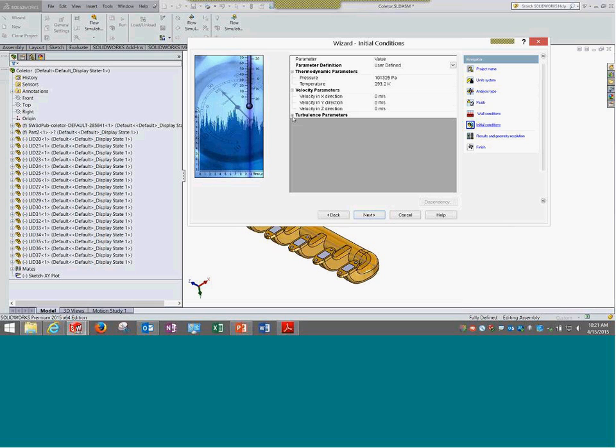Okay, there are different ways, but one of the common ways by which I explain this is that we are asking the software to start from an initial scenario. So when I start this analysis, the software does not know where to start, and it basically starts from zero, or ambient pressure and ambient temperature. However, if you have taken those initial conditions from some other project, or you are manually giving them to the software, honestly, you are helping the software to start with a closer solution, and then it can further iterate to give you the final, most accurate analysis result.